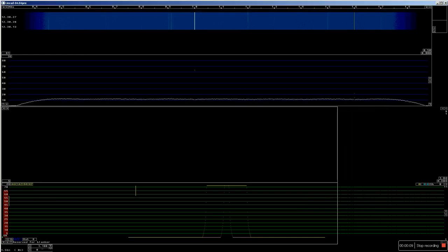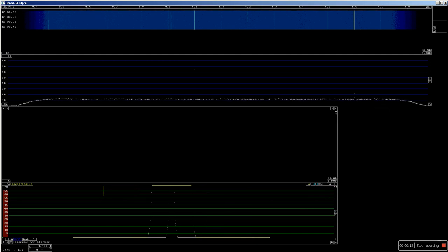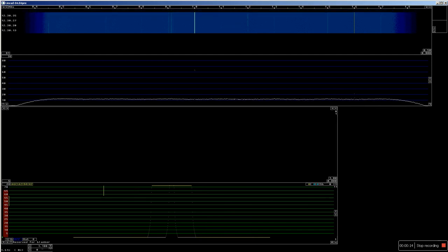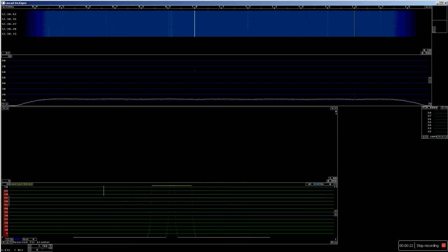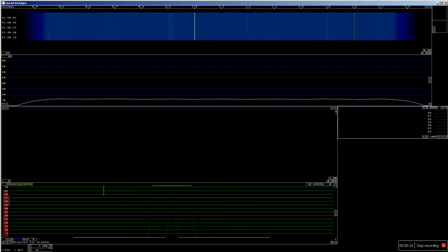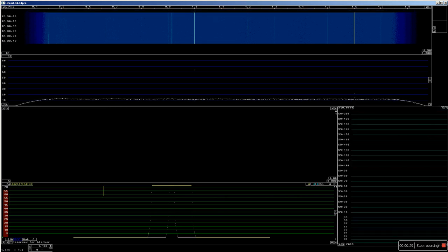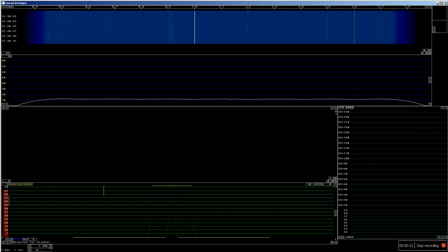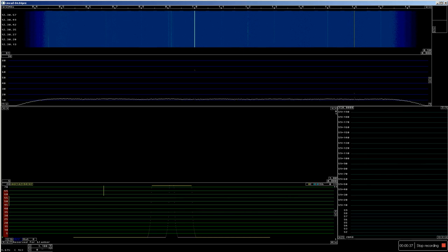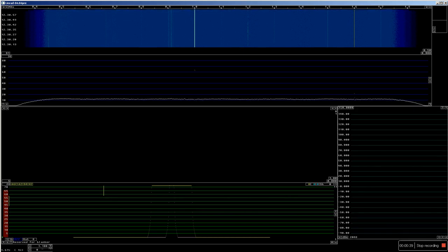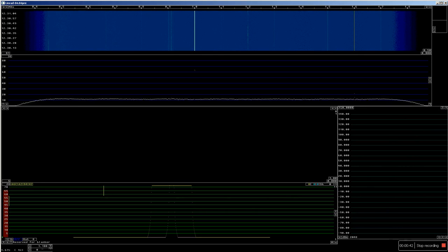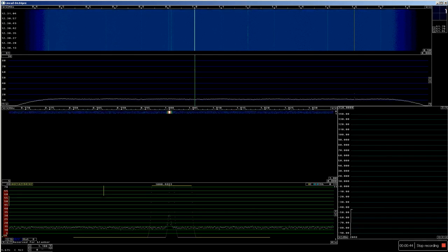I have to make room for the S meter somewhere. And I click here on the S, upper right corner, it's just now placed, to open the S meter graph, and I make it a decent window. And like that. And then I click on the S in the lower left corner until it shows dBm, and select the signal here,